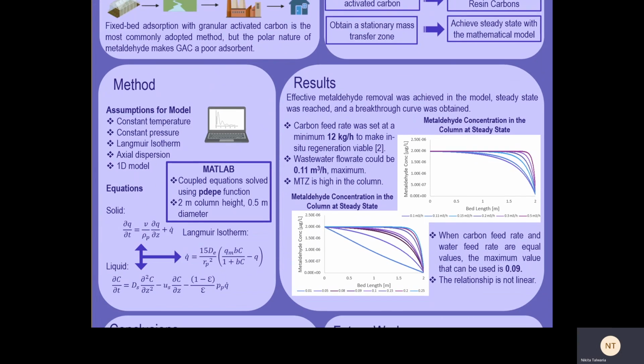Partial differential equations were derived for the solid and liquid phases, but the only connecting term between the two was Q dot, present in the adsorption terms. Isotherms are commonly used in adsorption kinetics, and here the Langmuir isotherm was used to connect the equations in MATLAB. The PDE-PE function was used as it removed the need to discretize the PDEs by hand, and it had MATLAB solve them directly. The results showed that effective removal could be achieved, but only at low wastewater volumes.